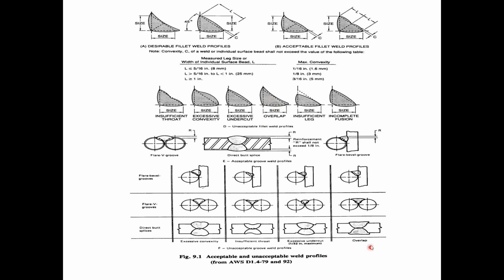This one here, the overlap where you've got weld that's overlapping more weld, is not illustrated very well right here. I think it's better illustrated on the bottom right, where you can see these were two bars that were trying to be butt welded together, and you started and made your way all the way around the back side of the bar, and you're coming up the bottom, and then you see here where that weld just sort of overlaps. It's not saying that you can't continue to weld until these are all melded together. What it's saying is this overlap is sort of deceiving because it looks like the two are connected, but it's really not. There's a cold joint between this weld and the weld underneath. So that's what is better illustrated, I think, by this diagram down at the bottom.